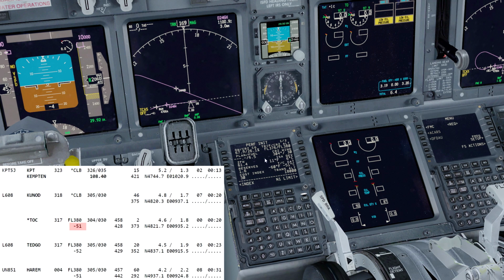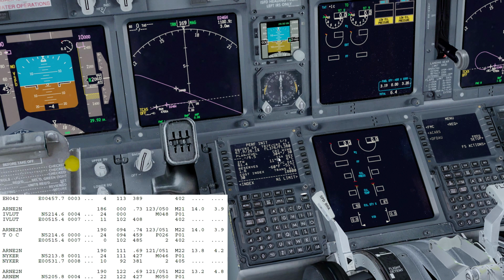That's what this ISA deviation states. You might also see something like P06 or M03 on your flight plan, indicating plus 06 or minus 03, and then you put that in the ISA deviation. So instead of entering an actual temperature at the top of climb, you may also see a plus or minus temperature indicating the ISA deviation.